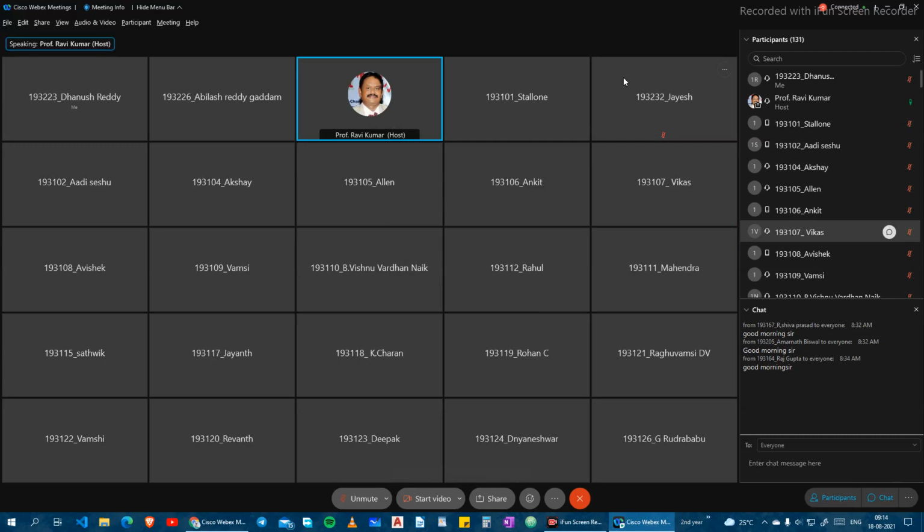Whenever power is developing, if you take a four-stroke cycle, suction, compression, expansion, exhaust, only in the power stroke will the piston move down forcibly to the crankshaft. The crankshaft will be rotated one cycle. Then the crankshaft is connected with a chain system to your back wheel to move it. The remaining strokes are idle strokes only: suction stroke, compression stroke, and exhaust stroke. Only in the expansion stroke do you get the power.